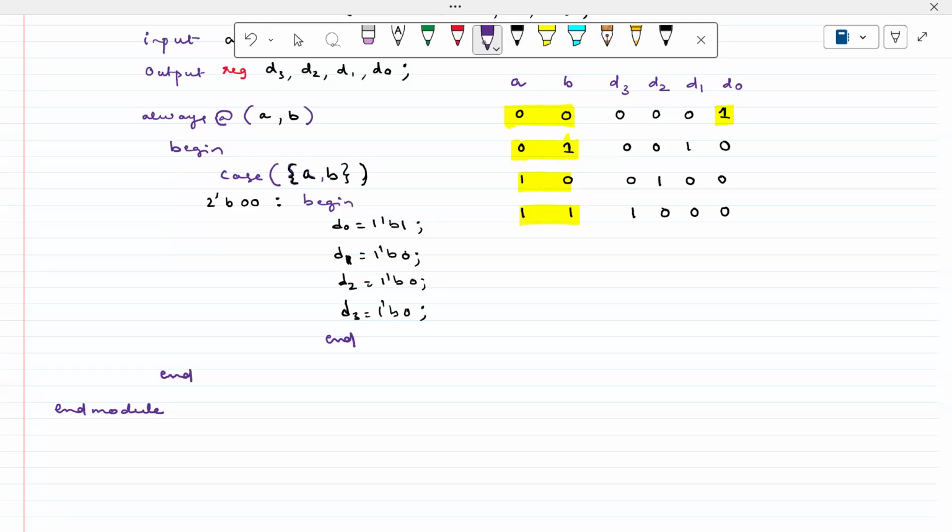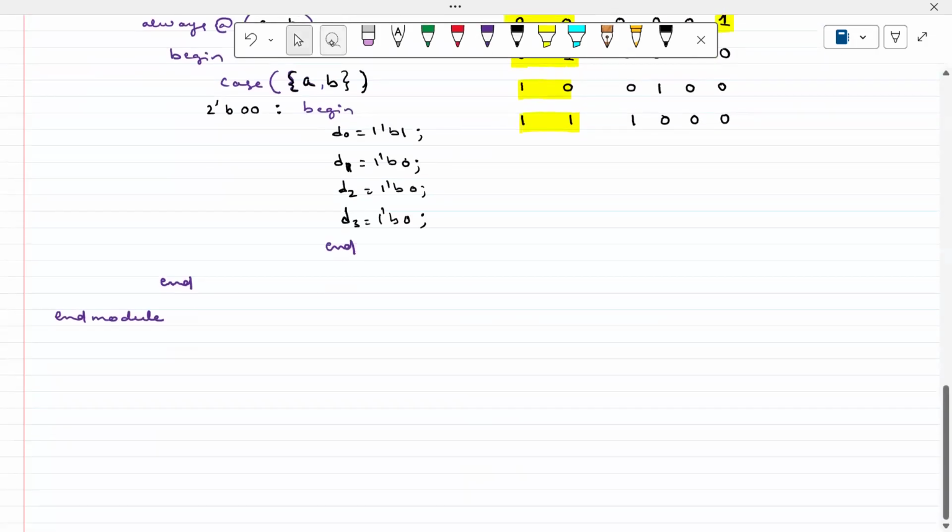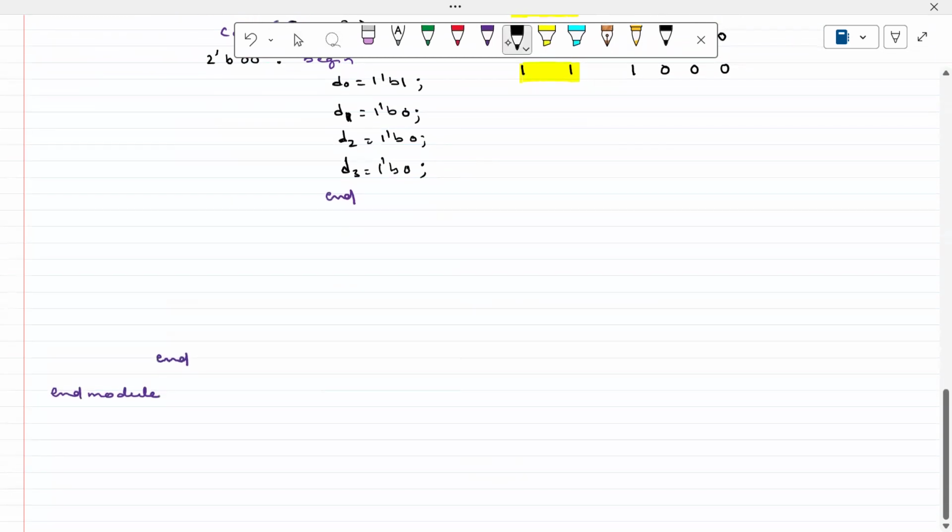If you want to write the second case, for example, I have to repeat the same thing. Instead, what I can do is modify this something like this. For the second case, I want 2'b01. I'm going to write it this way, effectively: I'm going to concatenate D3, comma, D2, comma, D1, comma, D0. This is a 4-bit size, right? The 4-bit 0010. So this is the simplest way that I can write. Are you getting the point?